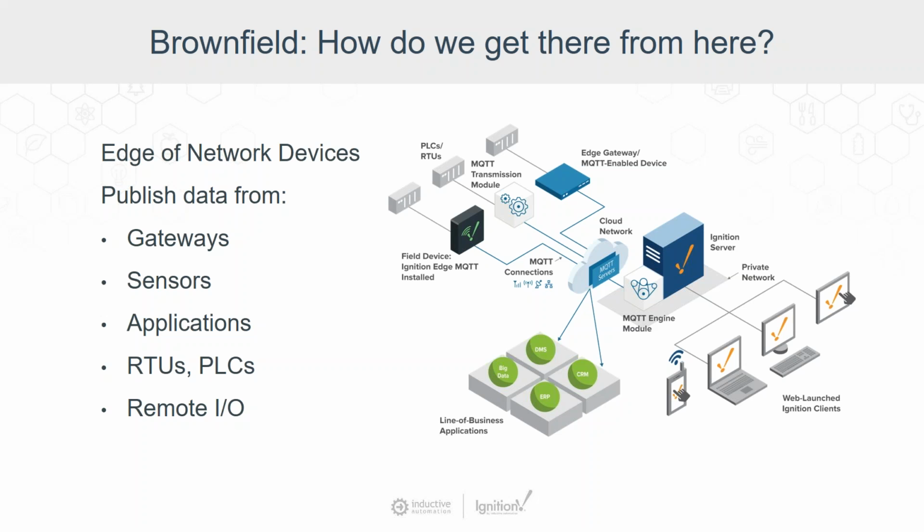And that is where we can deploy the Moxa hardware with Ignition Edge. We talked about that earlier. Ignition Edge is software that would run on that equipment and has drivers to PLCs through Allen Bradley, Modbus, Siemens, Opto22, SnapPack, DNP3, and more, and can bring that information in, do that protocol conversion, and publish it to an MQTT server. It could be on-premise, or of course it could be in the cloud, and we can do that securely.